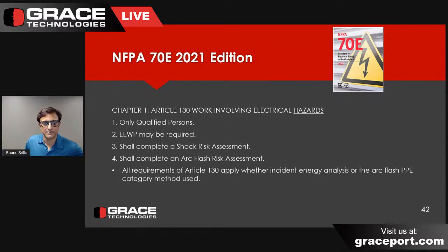All right, so again, the arc flash and shock risk assessments, I hope those are being interpreted properly because they're true risk assessments. Three steps. Work task: am I exposed to shock? What's the potential injury or damage to health to me? And what's the likelihood of occurrence? And that's the risk assessment right there that you're doing. You're using both of those to blend them and make a decision on the residual risk level.